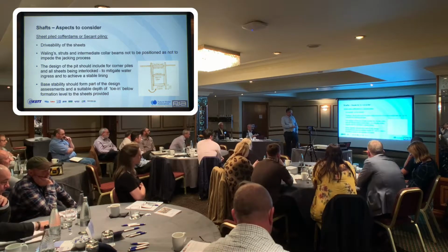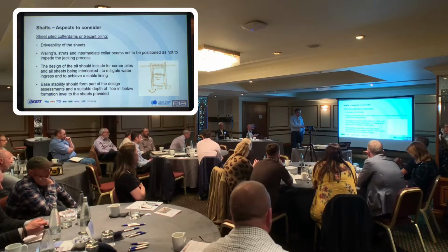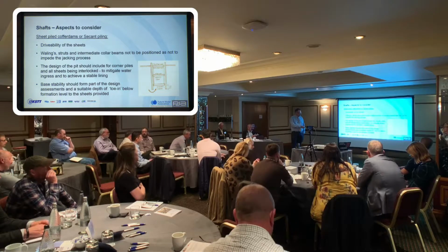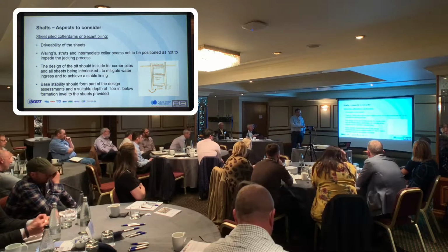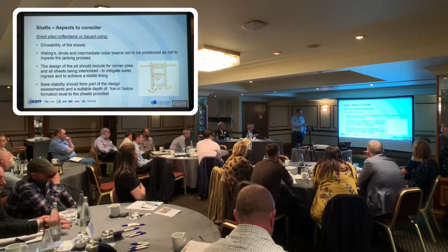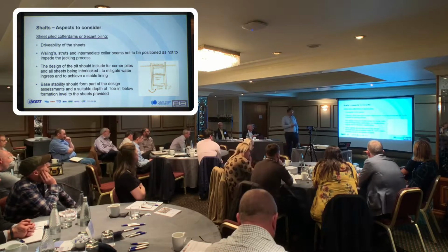The importance of that is obviously if you've got a high groundwater level up there and you've got a flow net, if folks can think back to the days at college, you've got a water pressure up there, and if you've not got sufficient cut-off down there to manage that water, then in the wrong ground conditions, so in granular materials, certainly sand and gravel, you could get boiling.